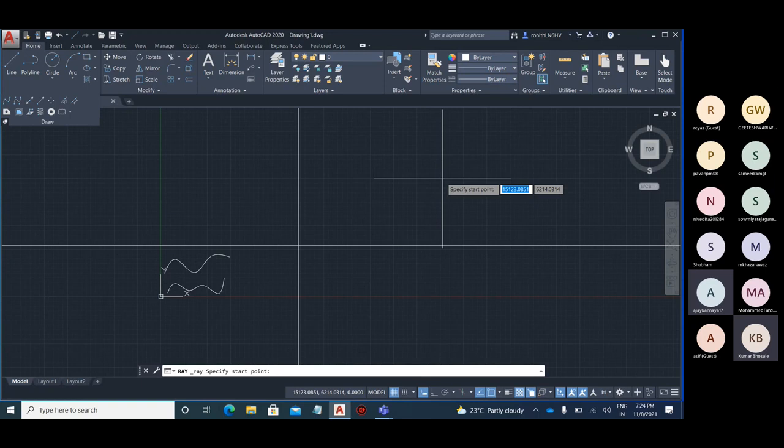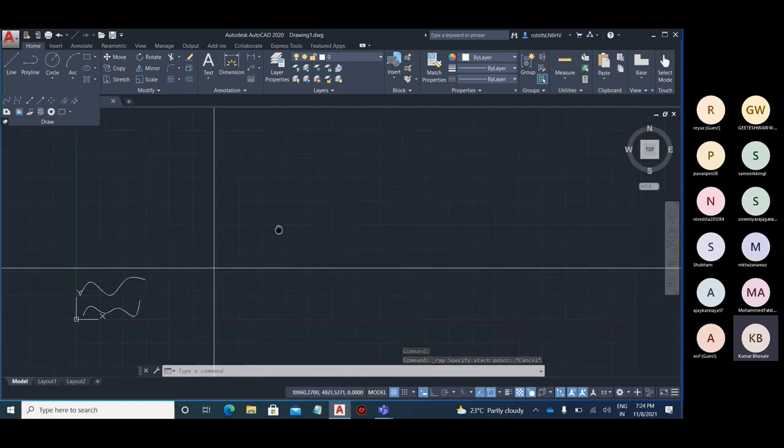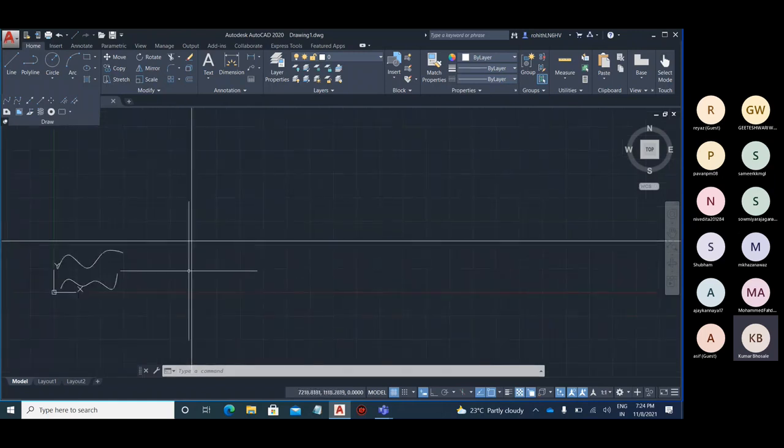Generally, if you don't want anything ending properly at the start only, when we'll be creating a plan, I will show you. Let's say I don't know where the end points of this line are. I don't know where the line is going to end for my plan. I am starting from one of the corners, so having offsets, creating walls, I can have a construction line, and at the end, I can just trim this off.